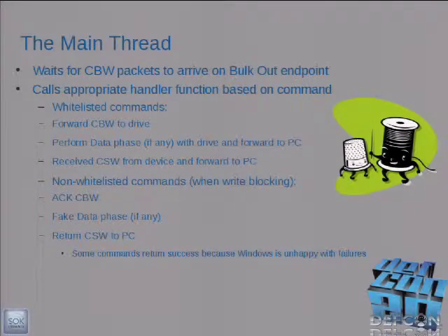Now, initially, in an early design of this, I actually returned an unsupported command status if you try to do things like format my drive or write to it. And what I found is that, strangely enough, Windows does not handle it correctly. So you tell Windows, unsupported command. What do you think Windows does? Tries again, and again, and again, and it never gives up. Right? It's really obnoxious.